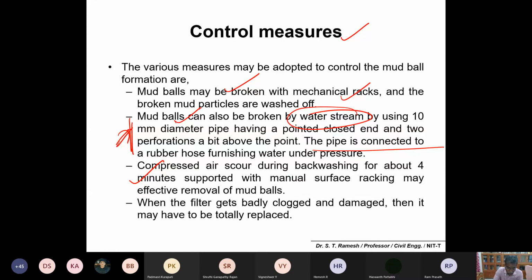That is something important. Okay, so please make a note: if the filter bed is open, you have a lot of problems with dust. It may also fall down onto the top of the filter bed during your operation, and it will also migrate down through the filter. During the movement, it will also form mud balls and occupy the space, and finally it will come down to the lowest portion of your gravel layer.